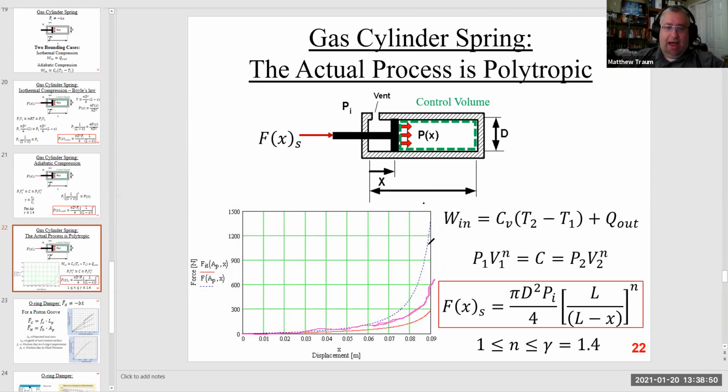And how high or how low that polytropic curve is depends on the value of N. The only way that you could really know that is by running an experiment, right? So you'd actually instrument a piston cylinder apparatus, do the compression, figure out what the temperature increase of the gas is, plug that temperature increase in here, solve for Q, and then determine the polytropic exponent based on the ratio between the change in internal energy and the heat transfer. So that's how that would be done experimentally.